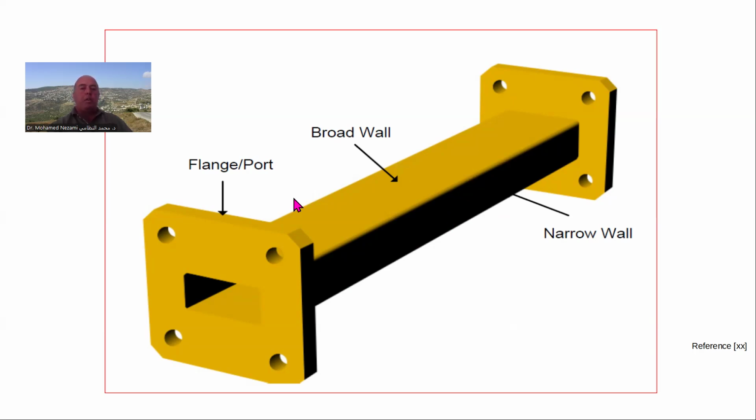Now, the slots in here can be longitudinal, okay? But in here, they can't be longitudinal because otherwise they will not radiate, because they're in line with the current. So you need to rotate them at an angle and you alternate the rotations so that you get consistent, uniformly emitting signal sources.